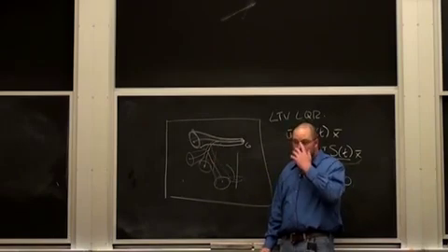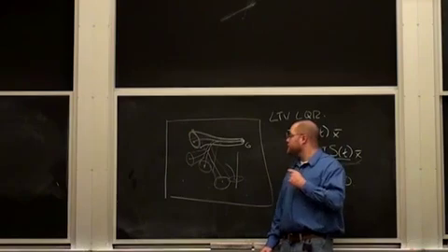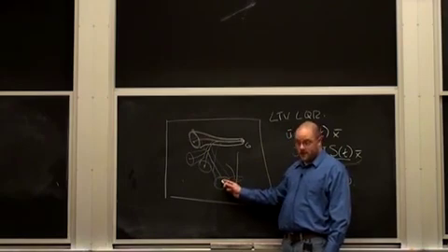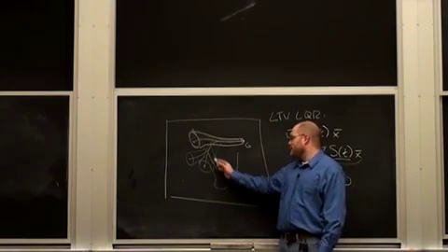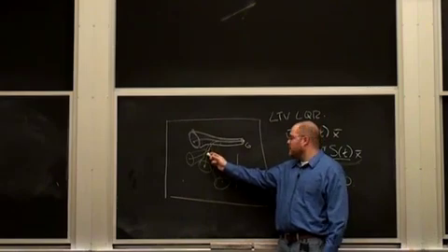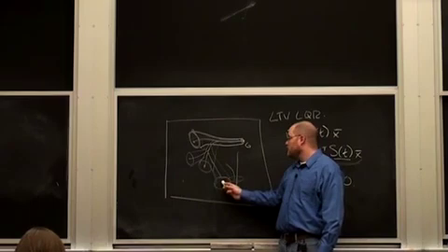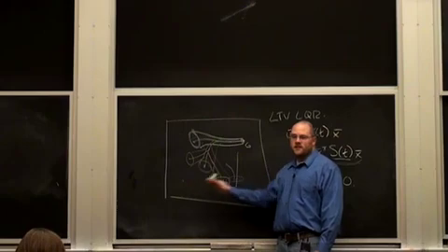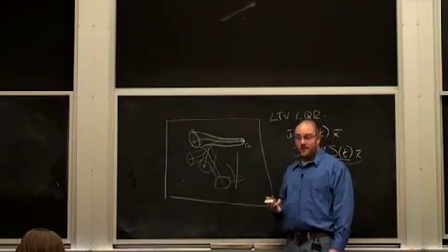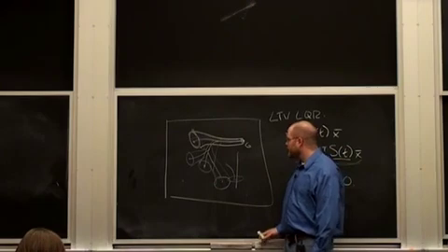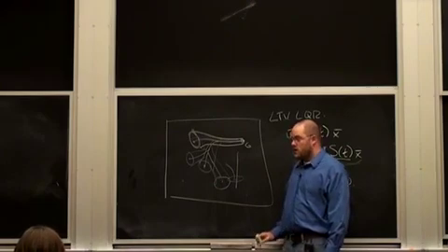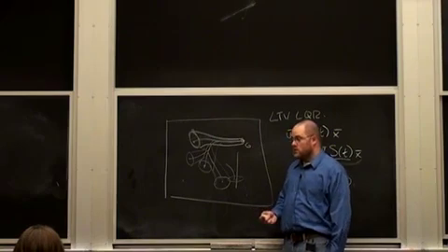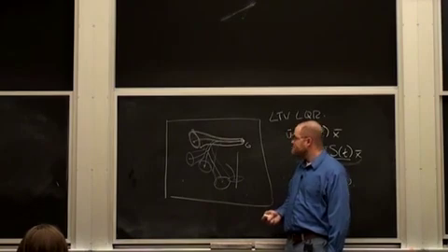Ernesto? And this just finds a feasible trajectory, not necessarily an optimal one. So whenever I design each trajectory, I use Dircol. Why not? So I can sort of say they're locally optimal in the branches that they are. Just because that's easy to accomplish, but there's no sense in which it's globally optimal, right? So I just try to say that every state will eventually get there, not that it'll get there optimally. Mm-hmm. But again, if you allowed it to sample inside the basins of attraction, you would probabilistically get some kind of convergence to global optimal.